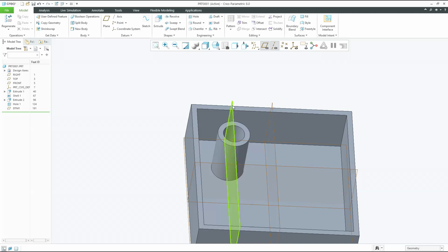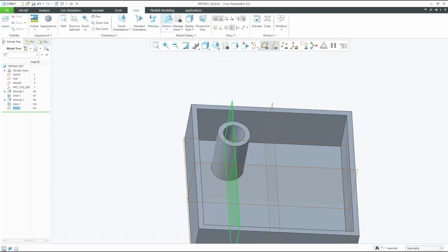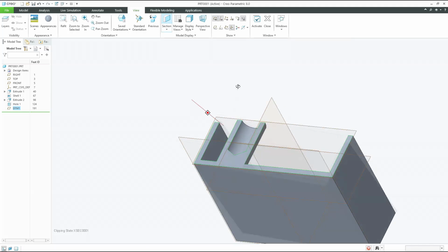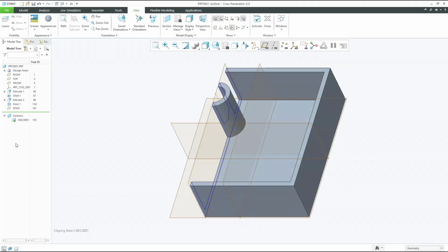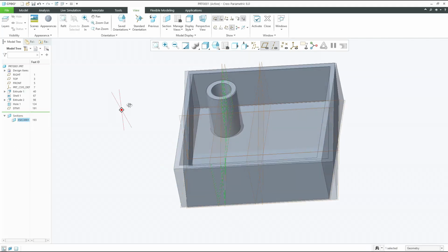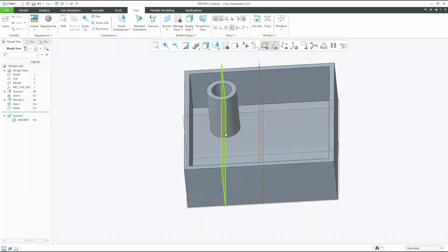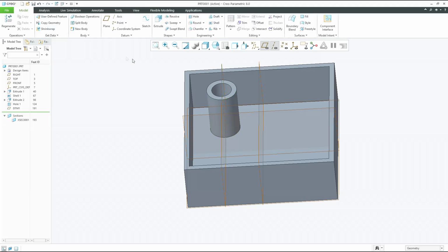Now you can have a cut section view through this plane and see how we have created the cylindrical boss and a hole in it. This hole is used to tighten with the neighboring parts along with the usage of nuts and bolts or studs or screws, whatever it may be. Whenever you are using such a fastener along with the boss, of course there should be straight stiffening ribs over the boss, or else due to heavy load or torque, the cylindrical boss may get damaged. So now we are going to see how to create a rib.